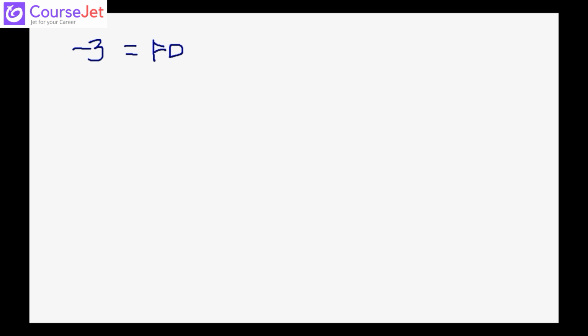The maximum value of 8 bits is 255, right? We are using timer 1 mode 2. In mode 2 you have only the TH1 register to be used, because it is an 8-bit mode. In an 8-bit mode the maximum value is 255. I want to count only 3. If you want to count only 3, you have to load the value 253, which is FD, then FE, FF. When you count this, your timer flag will become 1. That means one cycle is executed.